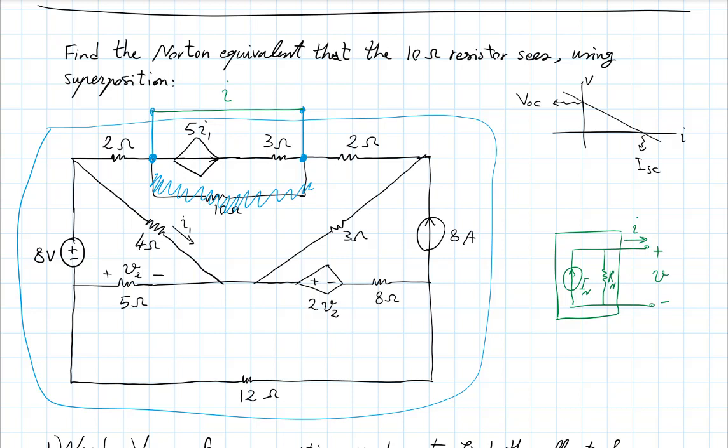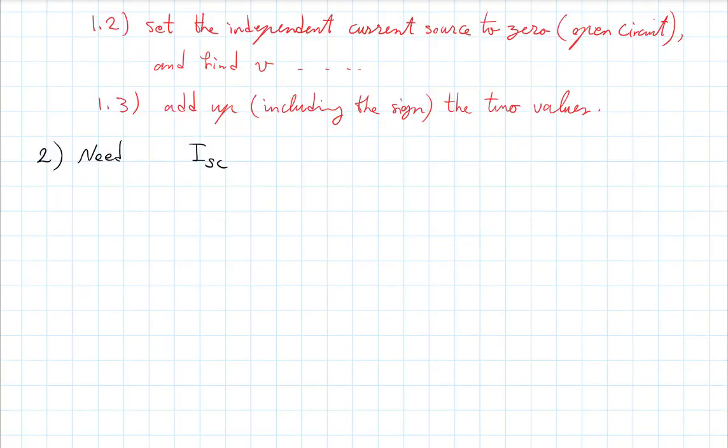So I have to keep in mind then that if I had defined my V like this, with that polarity, my I has to be like this. Okay? You see, although, as always, you can choose a convention that you want, you have to stay consistent for each problem within your choices, right? So we'll say here, pay special attention to the direction.